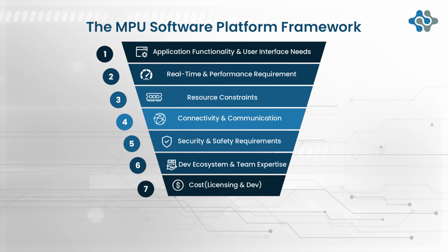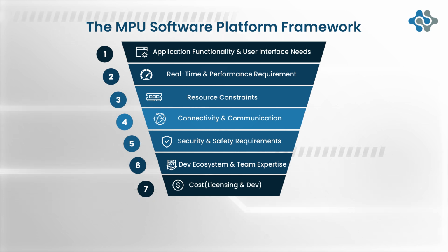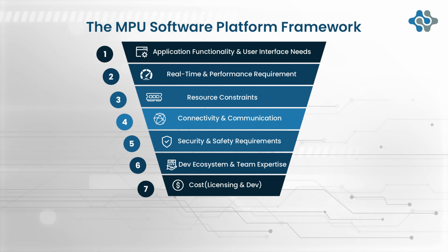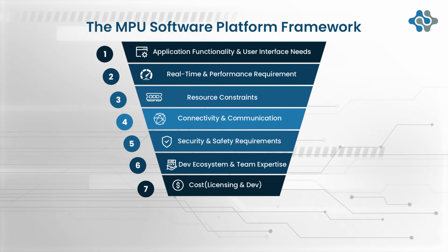Criterion 7. Cost. Consider both per-device licensing cost and the development cost. While Linux is free in terms of license, the effort to build, customize, and maintain a production-grade Linux distribution can be significant and requires specialized expertise.